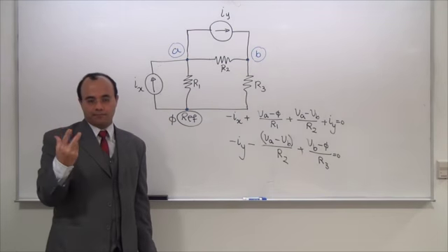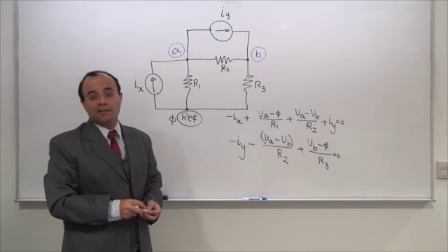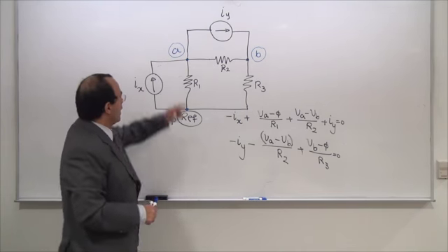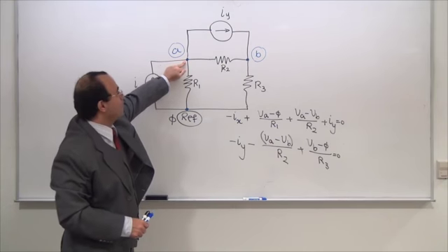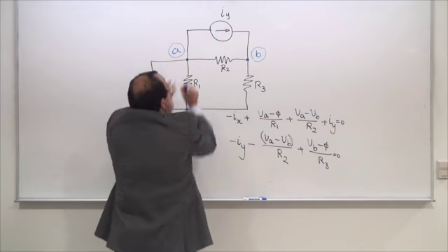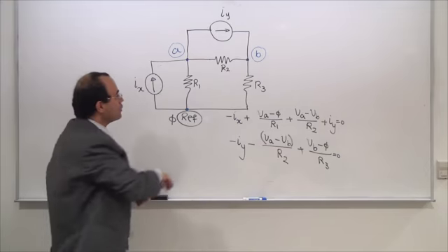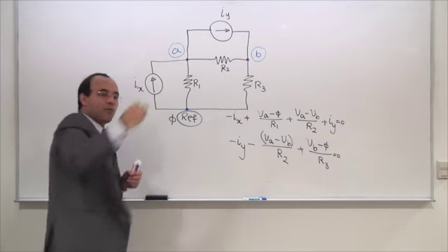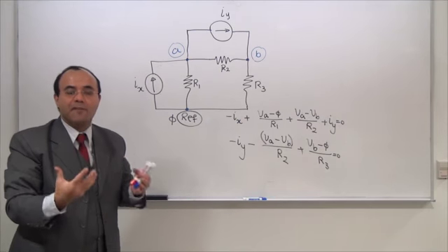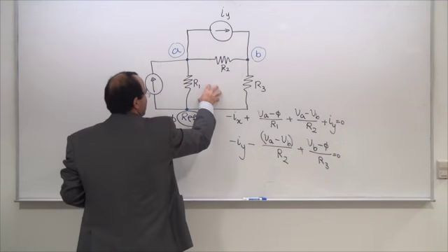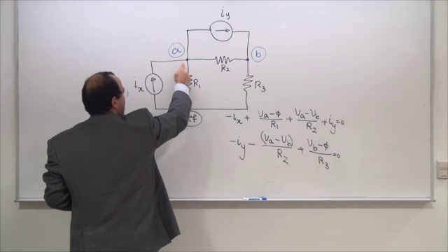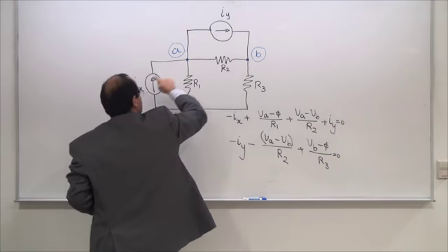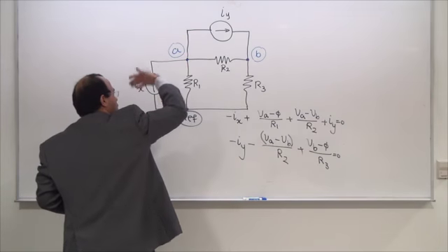I want to be an electron. I am a very small component, an electron. The electron is sitting on this node. Because I'm too small, I'm going to be self-centered. I'm not going to see what is happening around me. Because of that, I'm going to assume this is the biggest voltage. I'm actually offering the biggest voltage of the entire design. If this is the biggest voltage of the entire design, unless things are forced upon me by a current source, I'm going to say everything is leaving from my node.